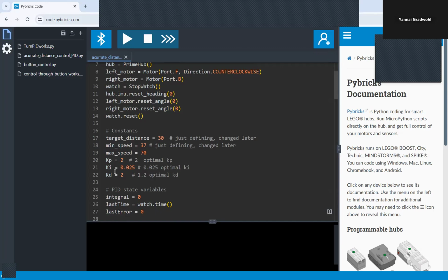The KI, or the integral term, looks at its past errors, like all the mistakes you've made before, and then adds them up over time. It basically helps remove any steady state error, like when the system gets close but never quite reaches the target. Thing is, too much KI makes the system unstable and can also cause oscillations or a windup. Basically, it causes everything to stack up. You could think of it as how much total error has built up over time that I still need to fix.